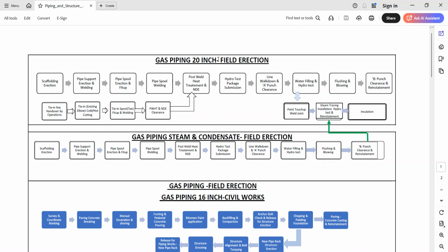For the pipe spool welding you may need generators and welding machines for the power supply. As it is a process plant, you may also need some kind of power source. For that you may need some generators, and a welding machine is also required in order to perform the welding. Here most of the oil and gas industry uses TIG welding. After doing the beveling on both pipes, you start the first welding, which we call root welding. They normally do it with TIG welding.